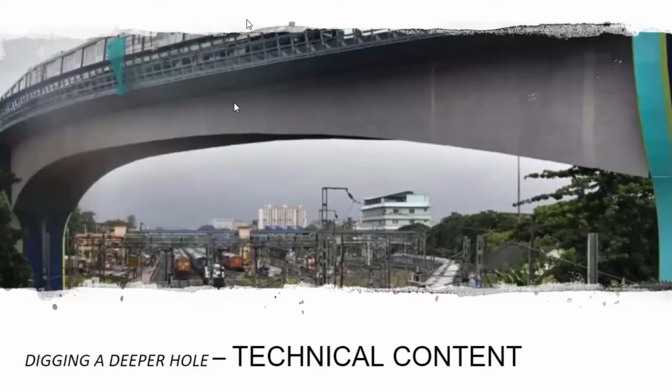So you see here that we have rails. It is basically a span which is going above the rail, and rail operations cannot be stopped. Since we cannot stop the rail operations, we have to find a technique that we can build a bridge across this railway without stopping these rail operations. So that means we cannot take a formwork from the ground up to this level and then construct this superstructure at our leisure by stopping the railway. We don't have that option.